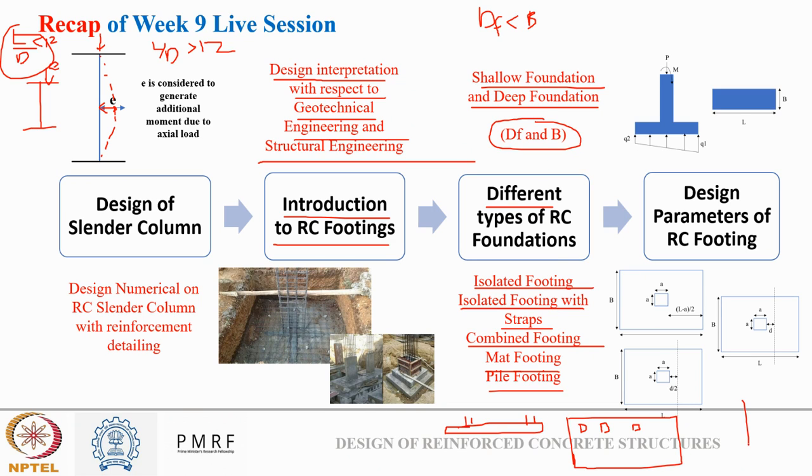So piles are generally circular or rectangular elements that dig deep into the soil. When my upper structure of soil is very weak and I need to go very deep beneath the ground, till stone works, then we go for pile footings. Okay. Then we saw different design parameters of RC footing, in which we first saw how we calculate the